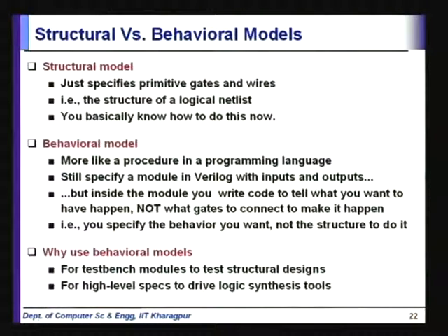to get larger modules. Now, today what we are going to focus on is the behavioral model. Now, behavioral model is more like a procedure in a programming language. Right? So, it describes the behavior and it still specifies a module in Verilog with inputs and outputs, but inside the module, unlike a structure like gates and wires etc., we can write code to explain what is happening inside that module. So, it is more like specifying an algorithm describing what that module is going to do.